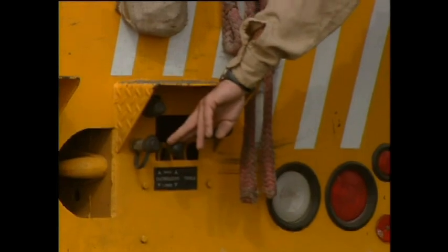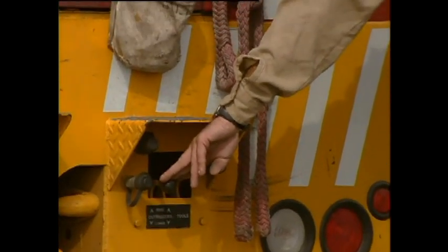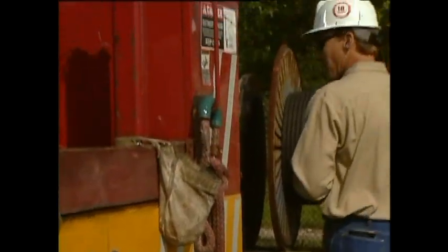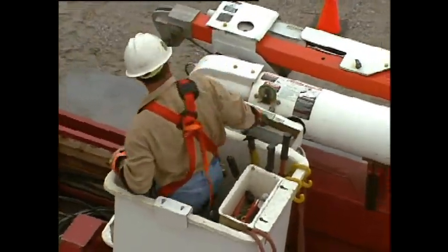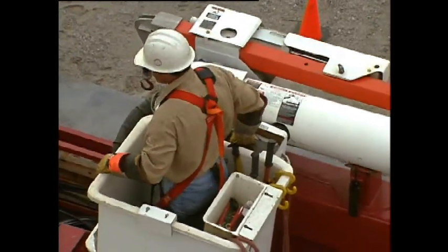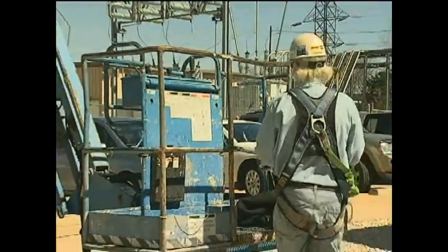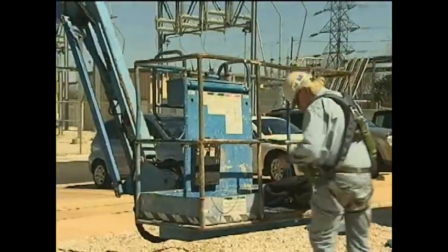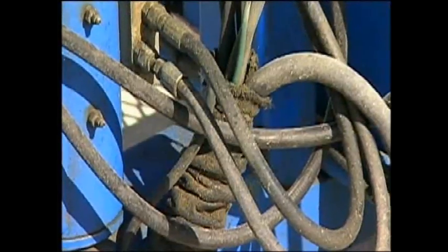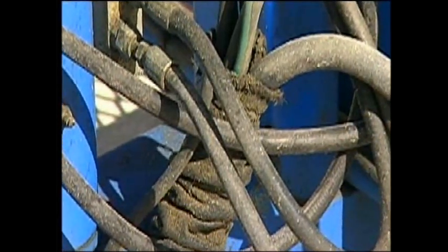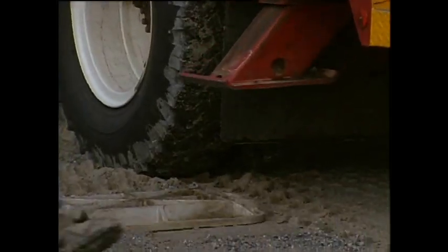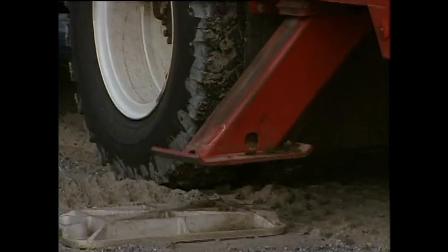Controls should never be forced from one position to another. Always inspect the boom for damage and/or any signs of weakness. If the lift is insulated, make sure it is dry and free of grease or oil. Check the guardrails. They should be free of damage and at the proper heights. Check the hydraulic system for possible leaks and the fluid level for proper amount of fluid. Outriggers should work properly and should always be set.